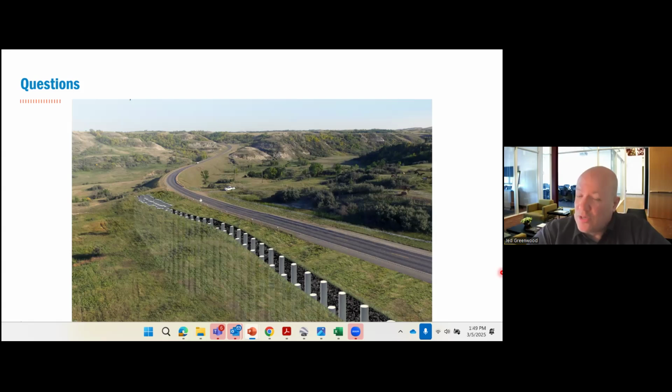Here we had a fairly large landslide, and so you can see there were quite a few inclinometers that were installed, and some were installed before we got involved in the project as well, and piezometers. But it really depends on the scale. If you have a reliable inclinometer and it's in a good spot and you think it'll last a long time, then yeah, maybe for a small landslide you can get by with one and it'll be just fine. But for a large one like this, we had to do quite a bit more.